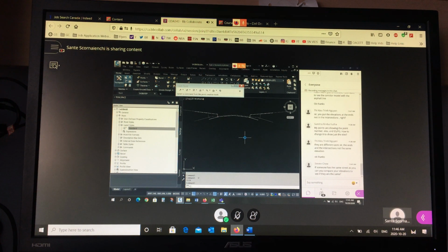Okay, so what that means now is, what's the elevation at the front lot corner going to be in the future? And the rule of thumb is this. From the existing center line, we're going to go up 0.3 of a foot, and that's the elevation we want to use at the street line. So whatever the existing centerline elevation is today, I'm going to use that number, add 0.3, and that's the proposed street line elevation. And that'll be compatible to the urbanization of the rural road to an urban section in the future. Okay. Does everybody understand what the design requirement is?